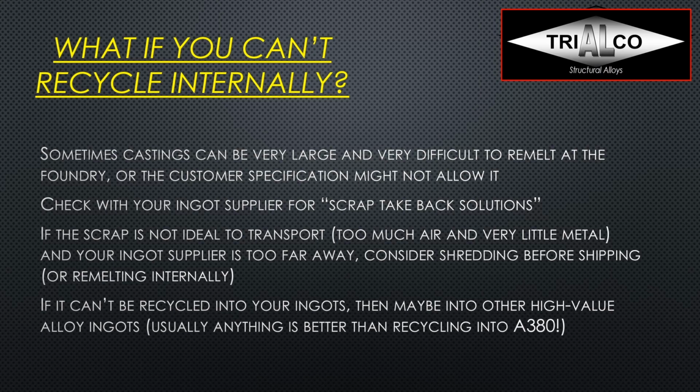So check with your ingot supplier for a scrap take-back solution, and if the scrap is not ideal to transport because it's just too much air and very little metal, and your ingot supplier is maybe even too far away, then consider shredding before shipping, or maybe remelting internally into something else, into another application, for example.